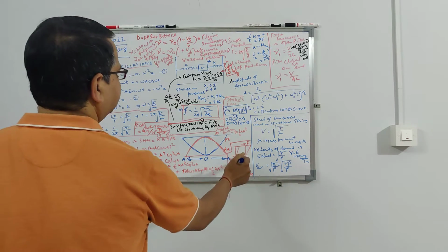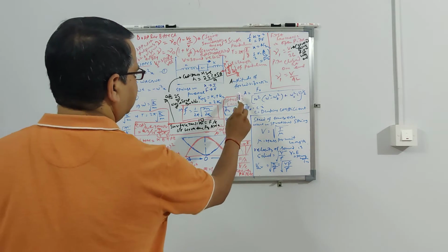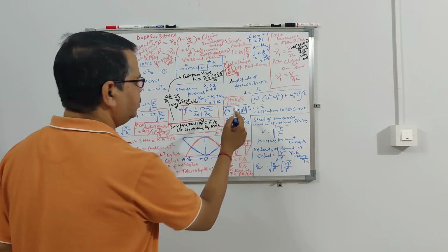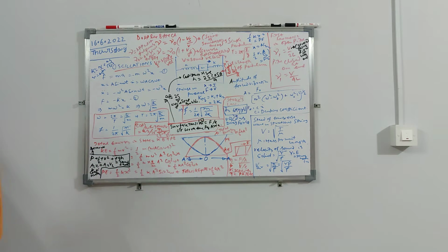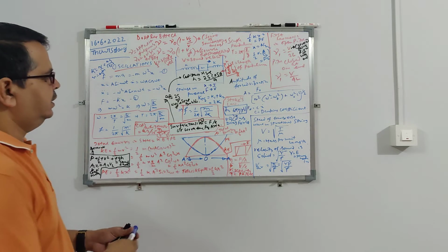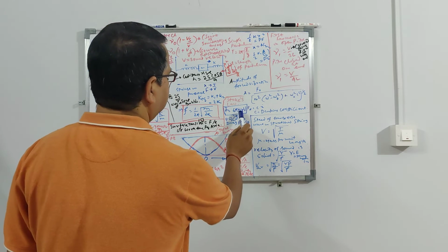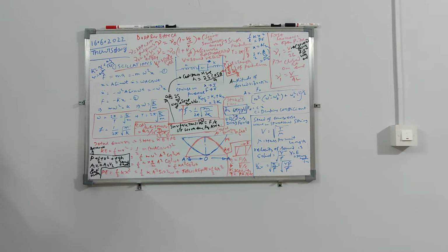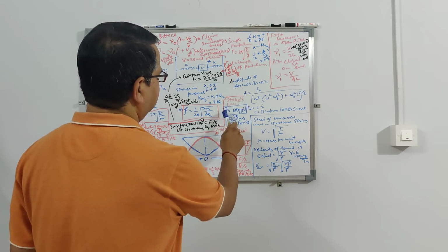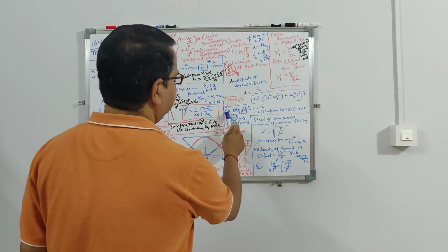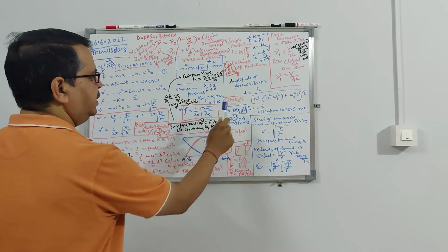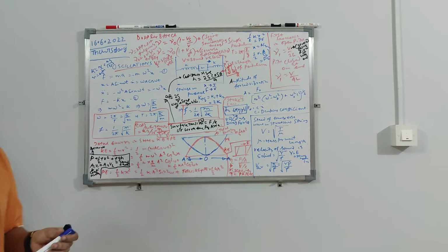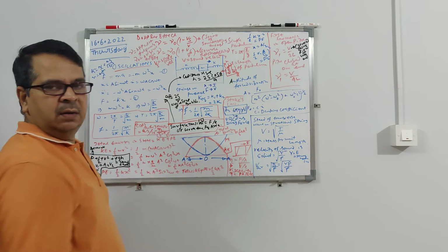And that is viscosity. Then another thing is Stokes Law. The viscous force exerted on a ball which is falling freely through a liquid is equal to 6 pi into the coefficient of viscosity into the radius of the ball and the terminal velocity. The resistance force depends on the coefficient of viscosity. Higher the radius of the ball, more is the force. Higher the terminal velocity, more is the force.